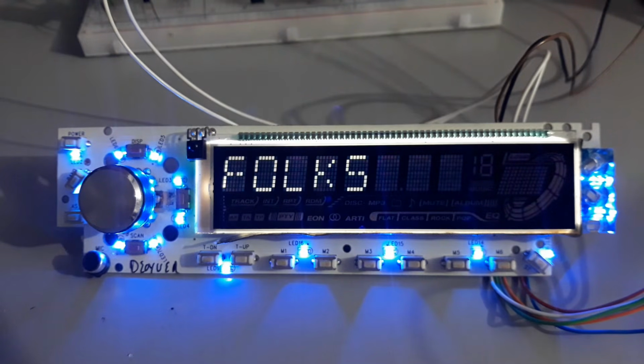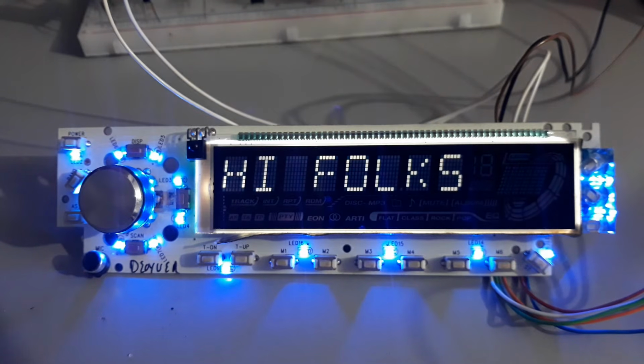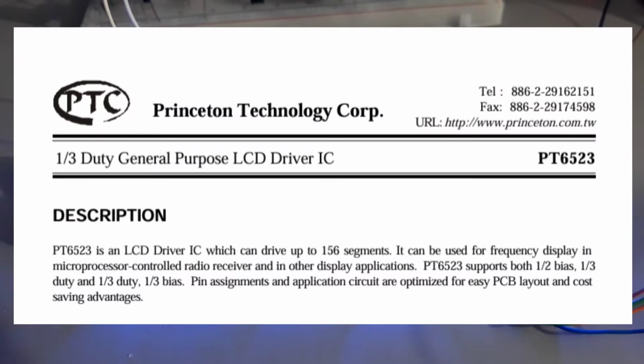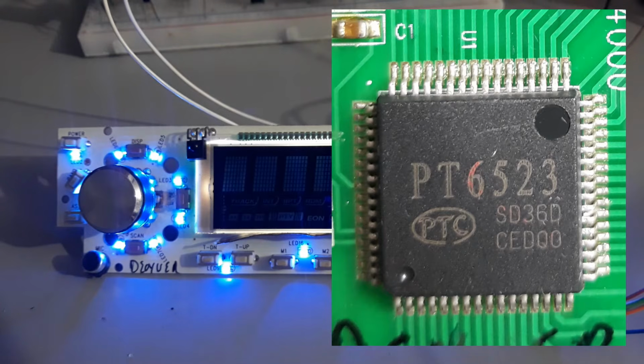We could not find the electrical schematics, so we had to identify the pins on the connector with a multimeter to be able to control the driver. The driver for the LCD is a PT6523.